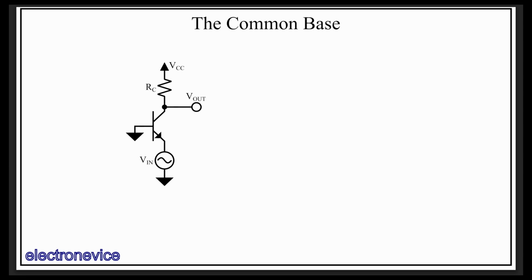So looking at the schematic here, just like any other transistor circuit, the common base requires a biasing current and biasing voltages, though it appears at first glance like it's a lot harder to bias due to the input voltage appearing to have to sink the biasing collector current. This makes the biasing more difficult for a simple voltage amplifier in isolation. However, we're going to skip the biasing circuitry discussion for now, as it can get a little ugly when setting it up in a straight voltage amplifier configuration like the previous transistor circuits. In practice, most applications make use of the existing biasing currents from other transistors connected to the common base to significantly simplify the biasing situation.